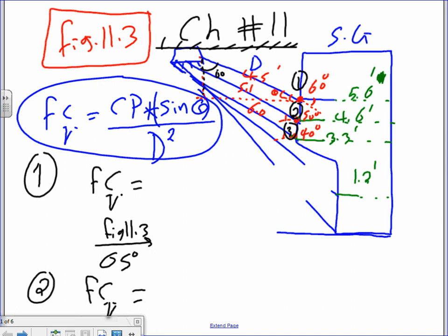again, the lighting book, it will tell you when you lay out your lights, if you have major equipment in this room, and you lay out your lights based on visual, the way we did it, and all of a sudden you find this lighting fixture right at the top of a big air handling unit, you will readjust these lights and relocate them strategically so they can give you the best performance of the light.